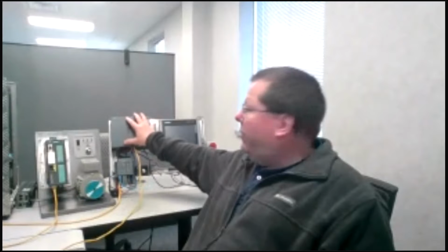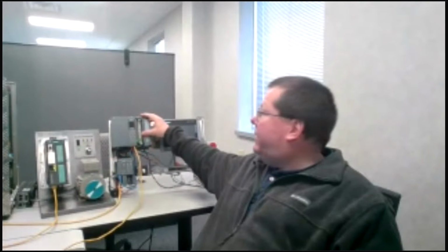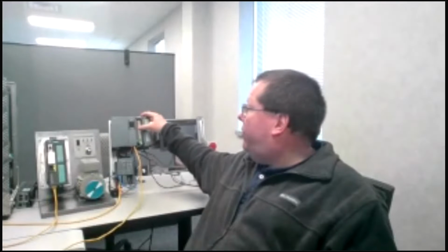Okay. We also have some other I/O built into our training demo. So we have the drive, the motor, PLC, and on the main rack of the PLC, we have a simulator card with some digital inputs and outputs on it so that we can actually toggle some of the bits needed to control the drive. Then down below, we have some remote I/O, which is ET200SP PROFINET I/O. And on that, we have an analog card that goes to a potentiometer so that I can turn the speed up and down for the set point on the drive.